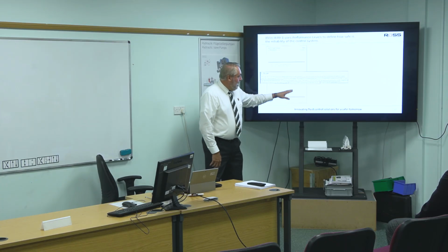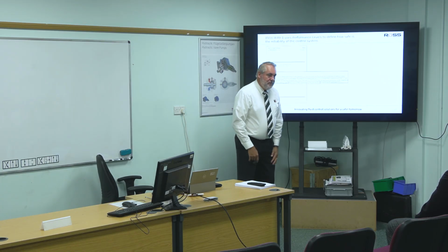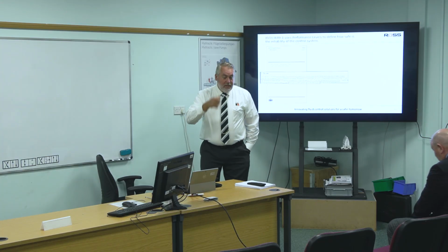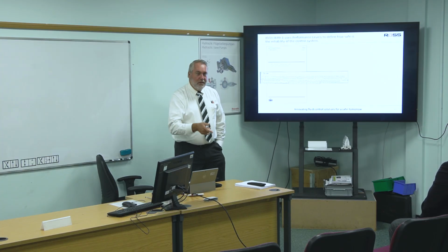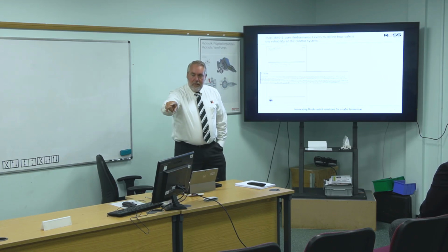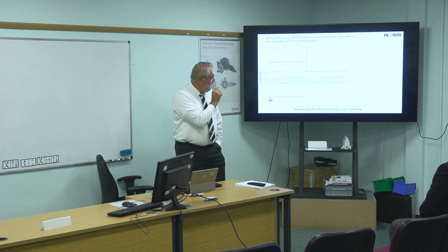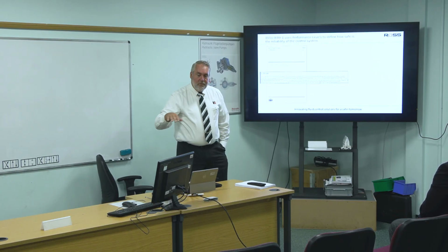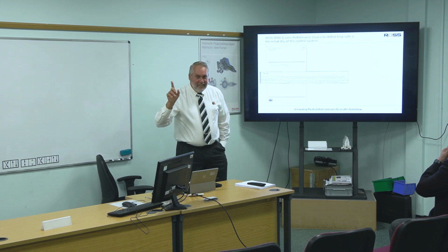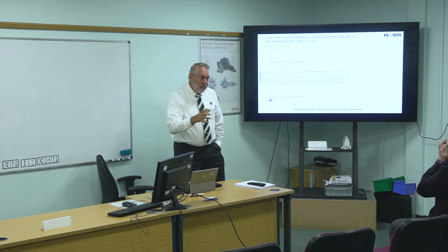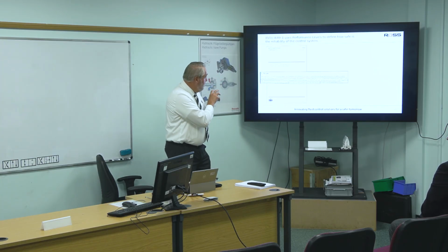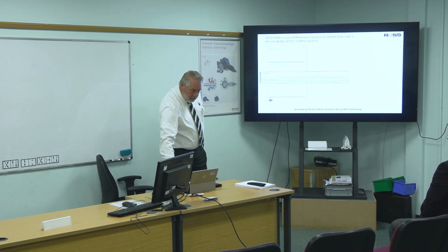And this is for what they call high demand systems. What we mean by high demand systems is it's got to be continuously ready to trigger. Meaning, I open that door, I'm going to dump that valve, or I'm going to reverse the direction of travel of that cylinder, whatever the safety function might be. That's called high demand systems. When you get into process safety, it's low demand, because you're not shutting that thing down but maybe once a year or once every 3 months. It's a different approach. But keep in mind that pneumatics and hydraulics is now part of that system.